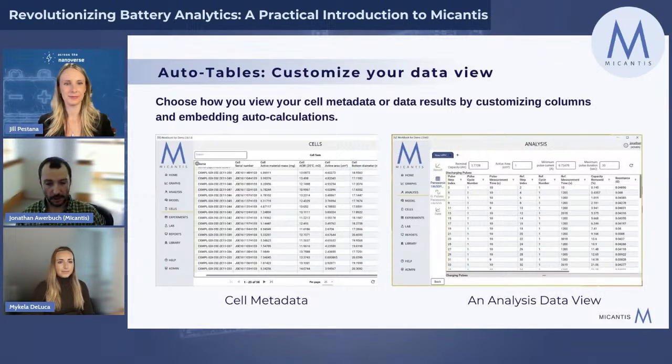So if you want to look at cycle 200 retained capacity or energy for every relevant cell that you test, we can configure that, and that'll appear here. Or cycle 147, right? It's completely customizable per customer, and those analytics get pretty advanced, so things like delta V's across rests, or Coulombic efficiency, or DQDVs, all those things can be reported in tabular form, updating in real time.